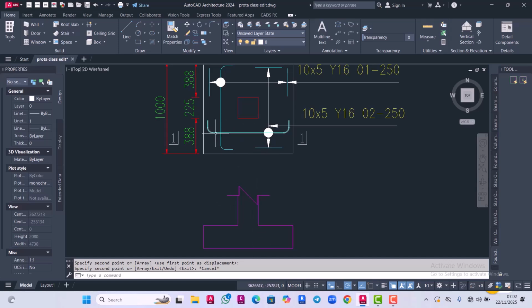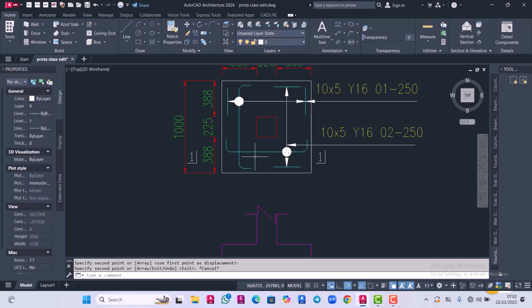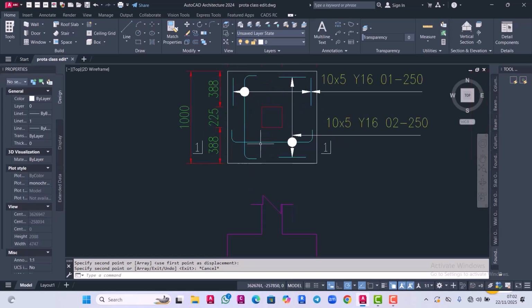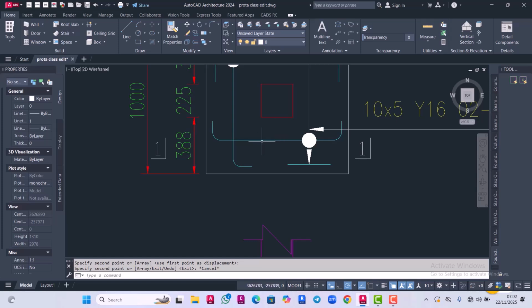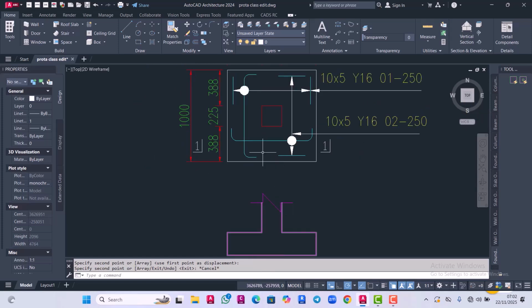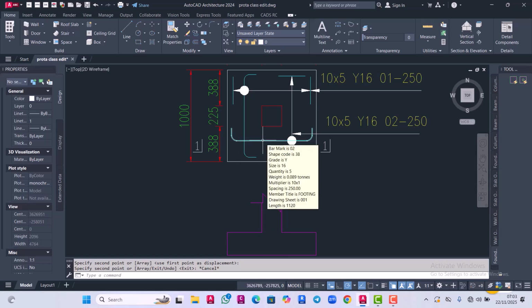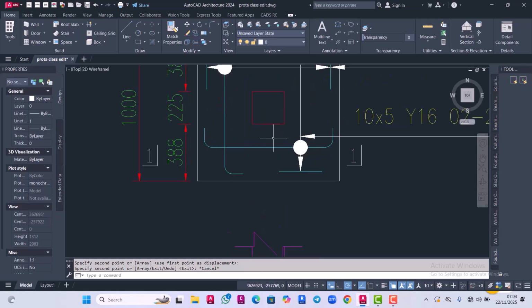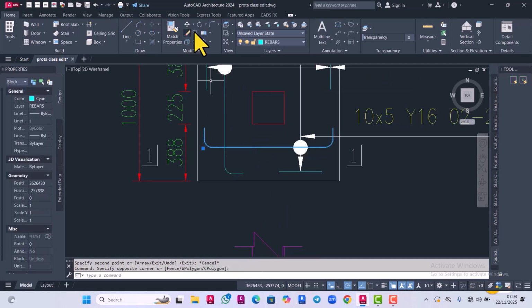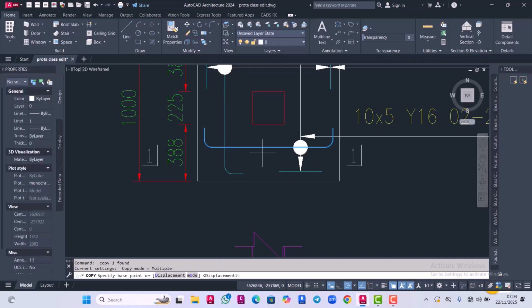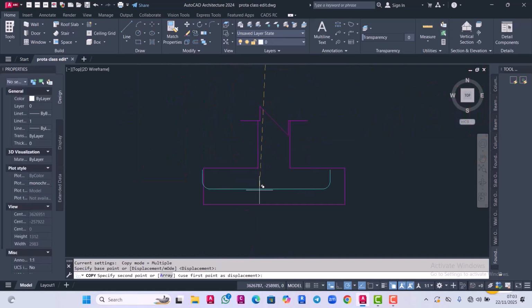All right. So a way we can do it is we can add bar view into this place. When you add bar view, we are not putting in any new reinforcement, but you only want what is showing here to show here. But if you don't want to use that, we can actually copy as well. Just click on this, click on copy, then you can drag it down to this point.